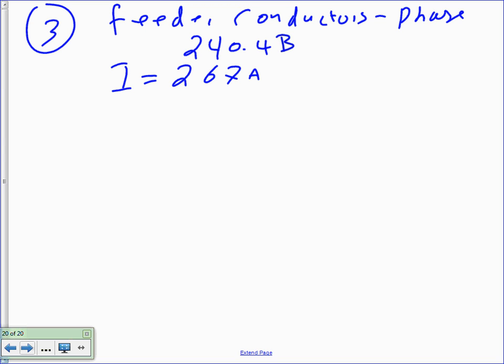So if you see it done in the field, if you're 800 or less, you can size based on the load as long as the next standard overcurrent protection device is higher. Like for this, is there any overcurrent protection device between 267 and 300? No. So if I put 300 to protect 267 cable, that's acceptable.